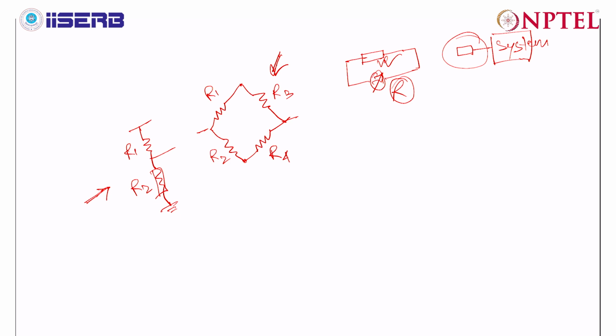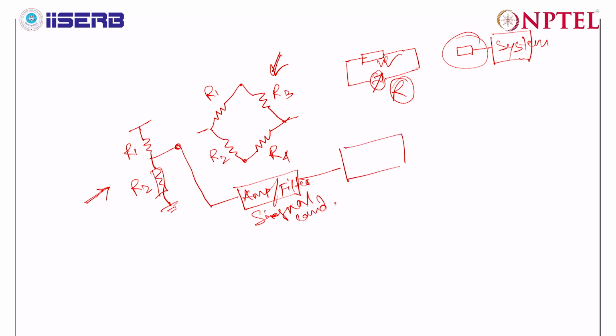You can connect this with a voltage divider circuit. I have explained before as well, but just concluding that you connect it in a voltage divider circuit, and then you take the analog output from here, and then you connect it to say an amplifier. This can be a filter, and then finally after this signal conditioning, you connect this with say a microcontroller or microprocessor, whatever it is. So you can connect it with a microcontroller or a microprocessor thereafter. But when you are connecting the sensor in a voltage divider circuit, it's also very important to decide what should be the other resistor.